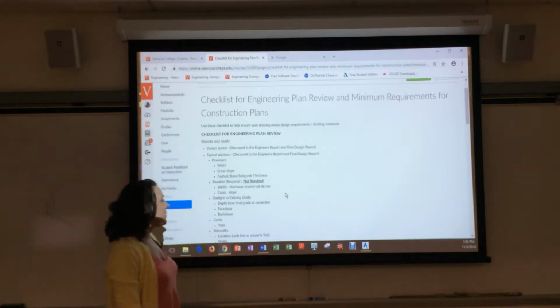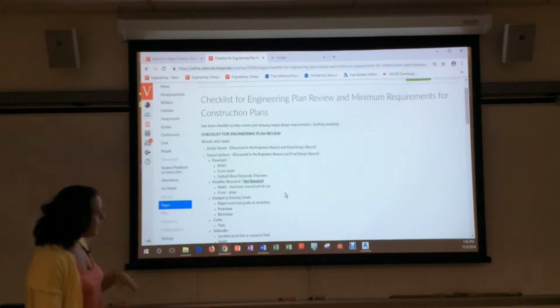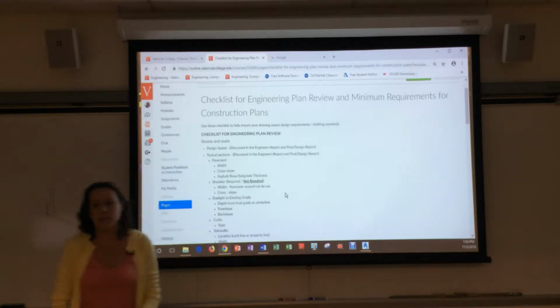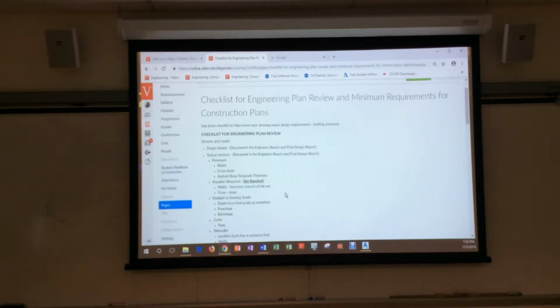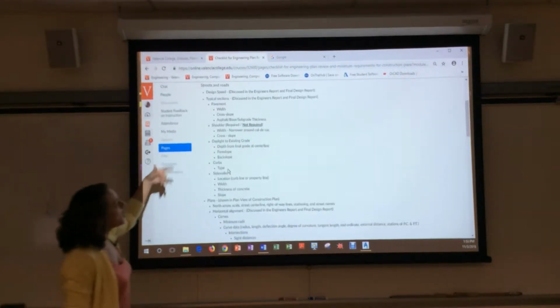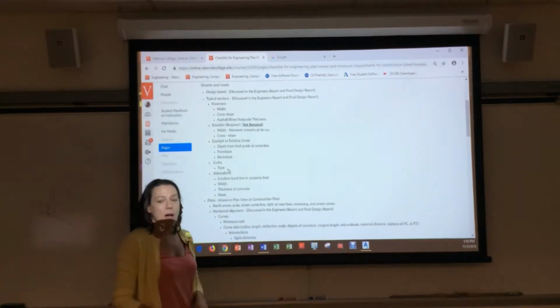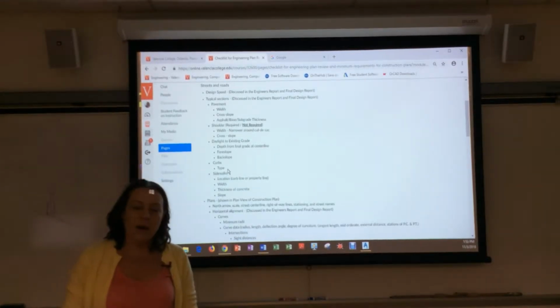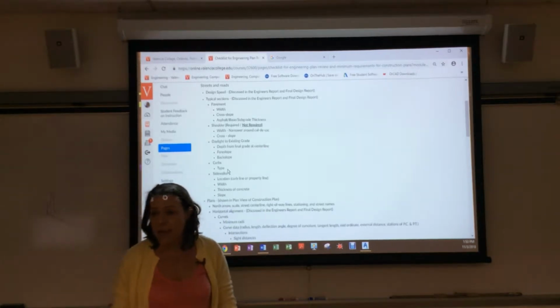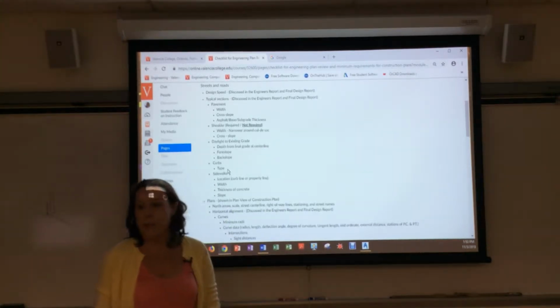So the depth for the final grade, the elevation of the final grade at center line, you've got foreslope and back slope. Okay? Back slope is cutting down to the ground. The curves, we're going to use a type F curve in this class because it's already set up in our templates. But be aware that DOT has a type A curve. They have what they call a drop curve or a Miami curve.